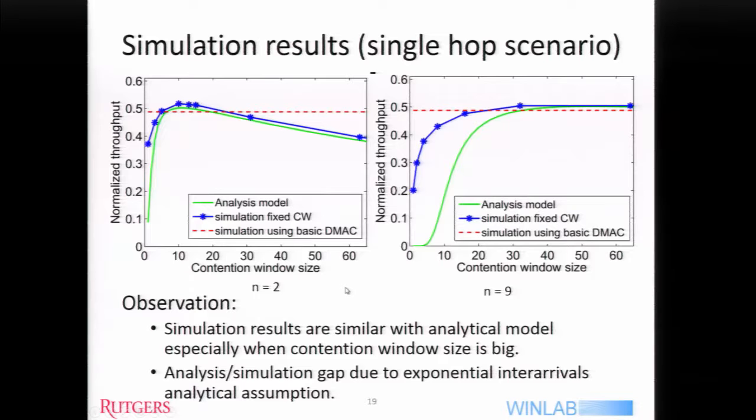I can imagine, and you're going to accuse me of being old, but I am old, so I may allow myself that. If I know the number of terminals in contention, I could advertise a TDMA window with n slots. After the overhead of having advertised that, and perhaps a little extra for deriving timing, I can push utilization to 90% of that. So as we start coordinating a little more, does TDMA become a little more attractive?